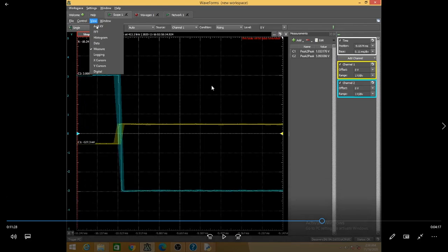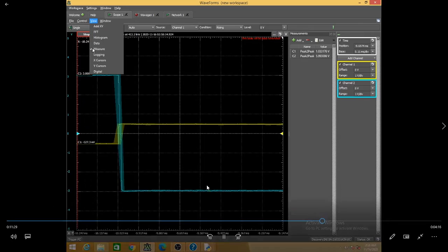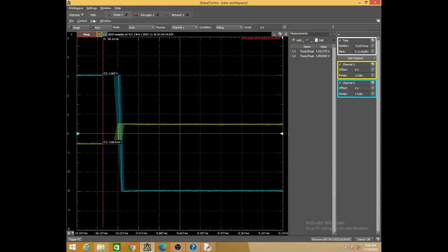So if the time becomes 0, does the entire ratio become infinity? Yes, sir. But it is not so. Typically, we're going to have some slew rate for the op amp that we are using in the lab. It's around 0.5 volt per microsecond. That is the slew rate.